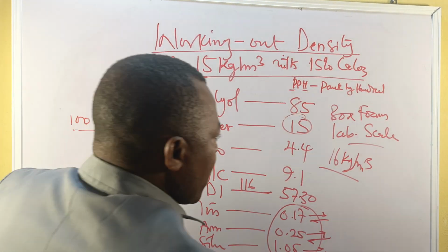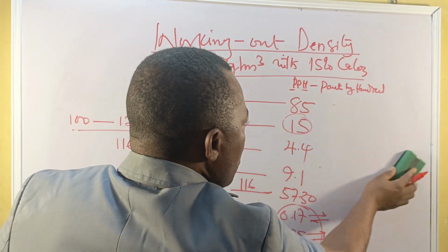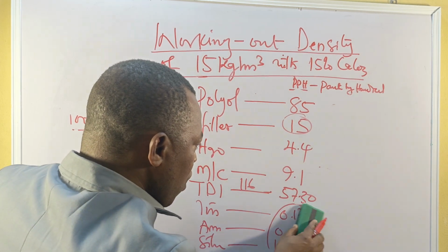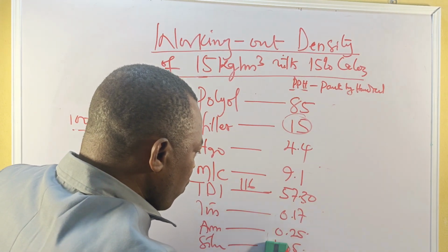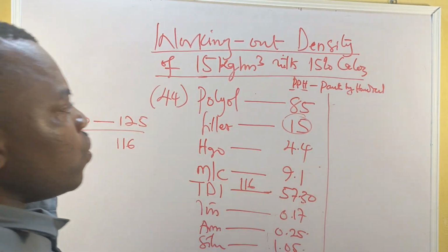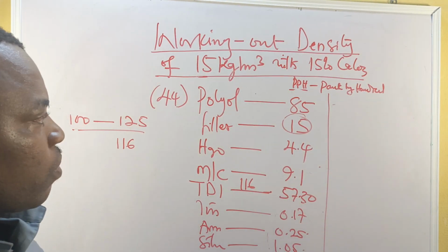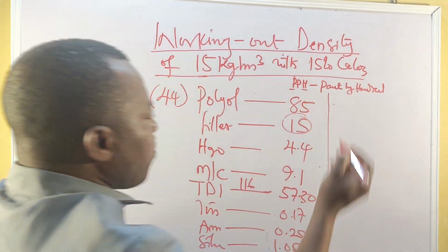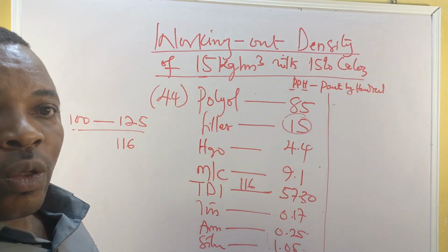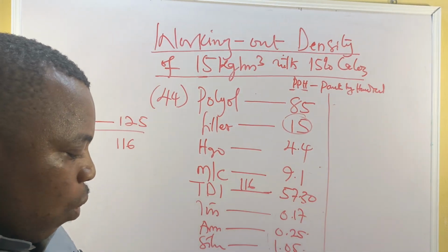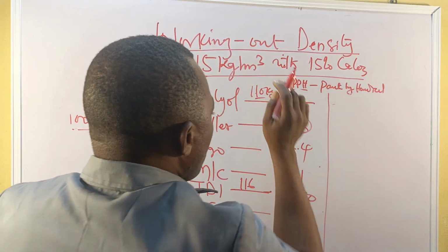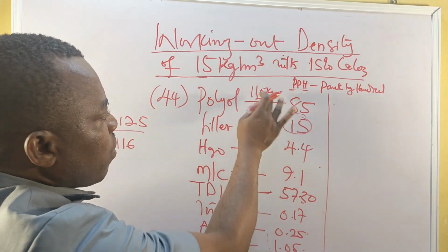For those of you that are using a continuous process machine, to convert this to a continuous process machine, for the conveyor to run, is very, very simple. Okay, how is it simple? What you need to do, you choose your output. Let's assume it's a low output machine, I can decide to say, okay, for polyol I'm going to use 110. So for example, you use 110 kg per minute. Okay, so in this case, that is including filler and this.